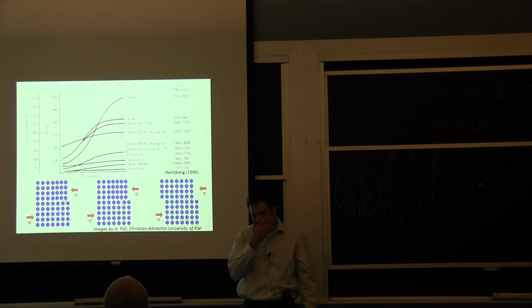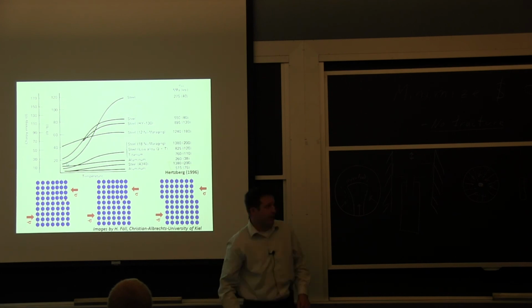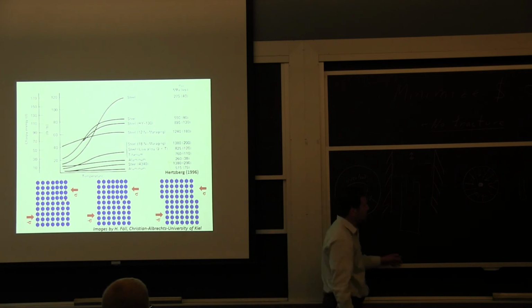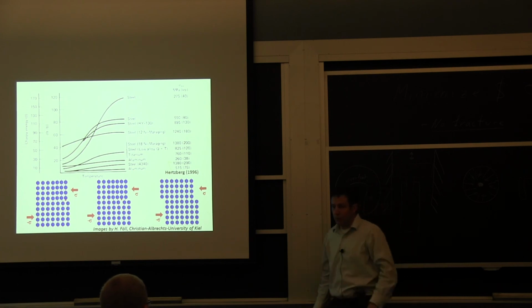What you find normally, and we have a bunch of materials here in this schematic, you can forget about the dislocation plot here, but we're looking at the energy it takes with respect to temperature to break. You see a lot more variation with steel than aluminum. So what happens with the steel at low temperature is this more controlling effect where you really start having some of this brittle behavior going on.